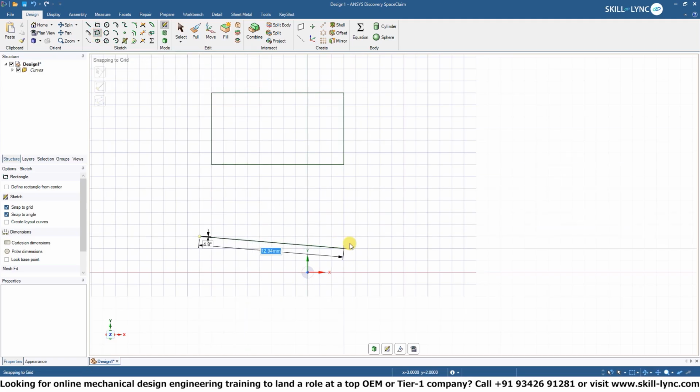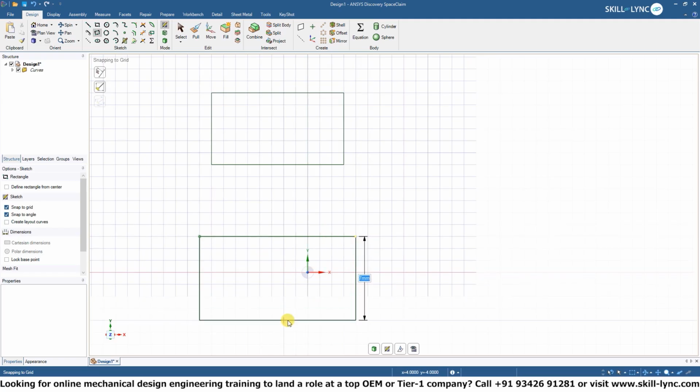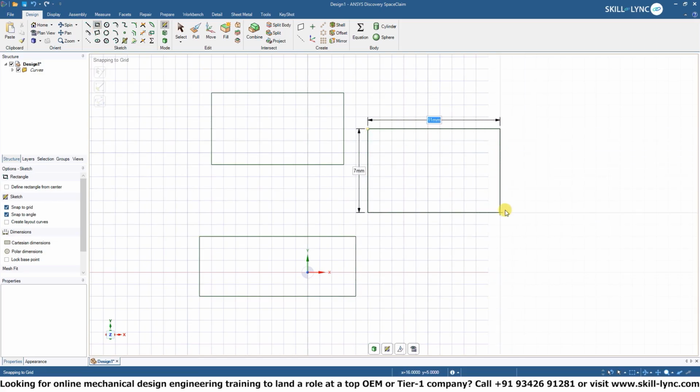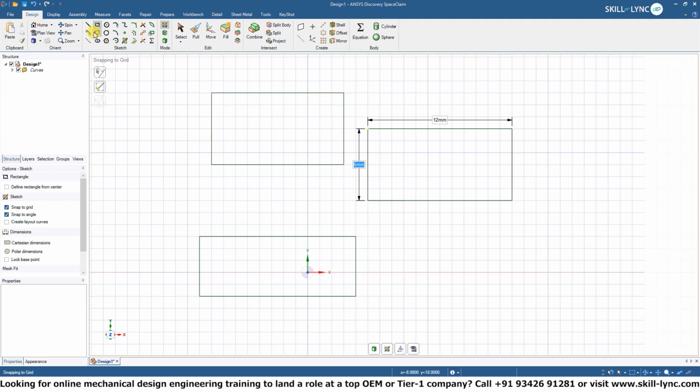So how this one works, you choose one side, so you choose corner to corner and then height. This one can give you more parametric control over it, right? So pretty much, when you use a corner rectangle, you're defining both the length and the height at the same time using one drag and drop motion. So pretty much you're drawing it from corner to corner. Whereas with the 3-point rectangle, it requires you to set the length first and then the height.